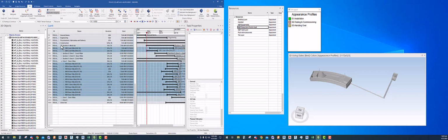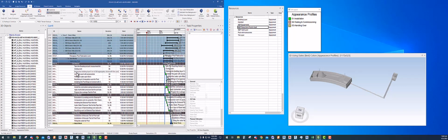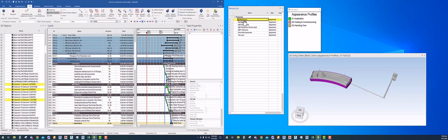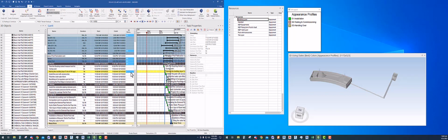Earlier also there were some, but I already did that, so you don't need to see. You just need to find 3BR dune villa. Now the first thing is we want the bedding layer. So this is the task, making the bedding layer: 5 cm of 3x8 aggregates mixed with sand. I'll select my bedding layer and click and drag up to here. Once I click and drag, you can see that the resource is assigned.